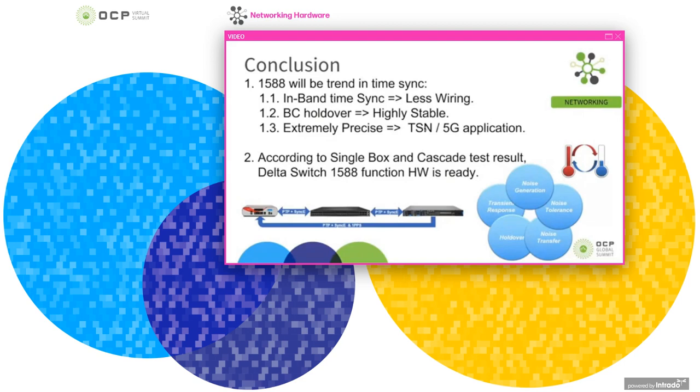And the second one is because here we use the boundary clock to achieve 1588, it retains a center time with a very stable OCXO, so it could hold over very stable. It means you have a highly stable system when you use a boundary clock. And the last one is it is extremely precise, because nowadays our boundary clock is aimed at 5G applications and for TSN. It is a very tight requirement in timing.